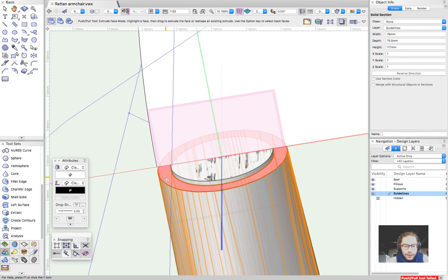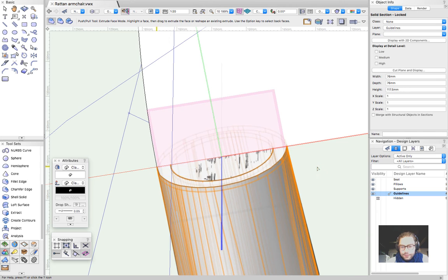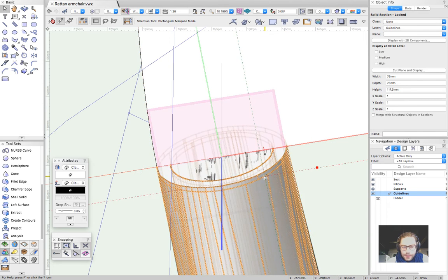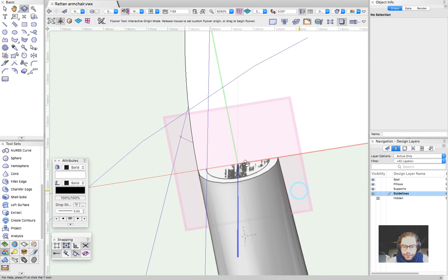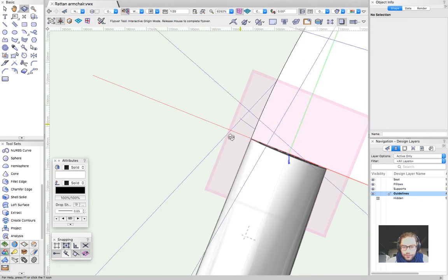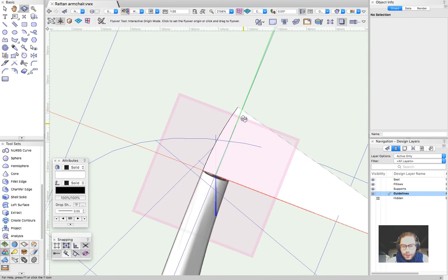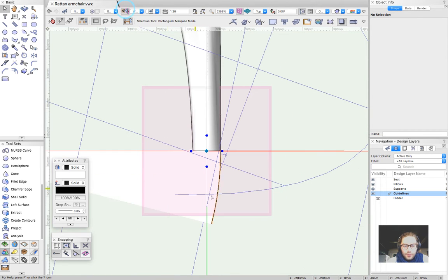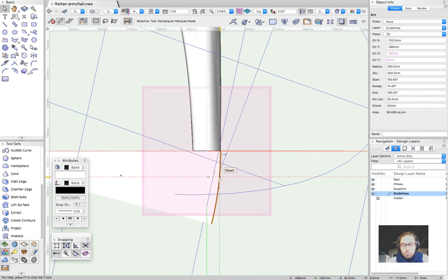But I believe that in the first mode, just straight extrusion, it will be working correctly. So it's a bit approximated, but it's just 1 millimeter. Okay. So I'm going to rotate the working plane so the perpendicular view will be looking normal.